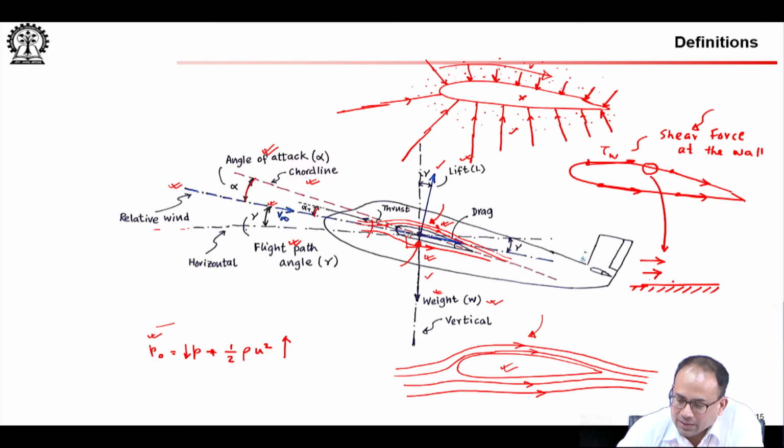But Prandtl established on a theoretical basis that when you have a flow like this near a surface and the flow has viscosity, the particles close to the wall will stick to it and stop moving, and they will try to exert through viscosity an effect on the neighboring particles to slow down as well. The particles here will slow down, these will exert a slowing down behavior on the next one. So, that way a velocity distribution is created.